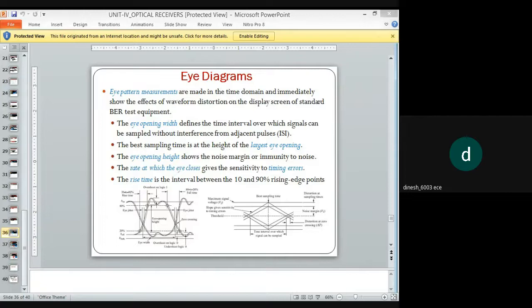If there are additional optical components in one of the transmission paths, then the signal levels arriving at the OLT could vary up to 20 decibel. A fast responding burst mode receiver with high sensitivity is required. The guard time provides a sufficient delay to prevent collisions between successive packets that may come from different optical network paths.